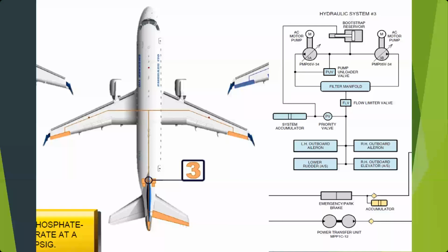The other thing you'll see is different flaps, ground spoilers and flight spoilers. Some of them are on the number 1 system, some of them are on the number 2 system. Okay. Brakes: the number 1 system does your outboard brakes on this aircraft, and there are 2 wheels on each main gear. The number 2 system does the inboard brakes.